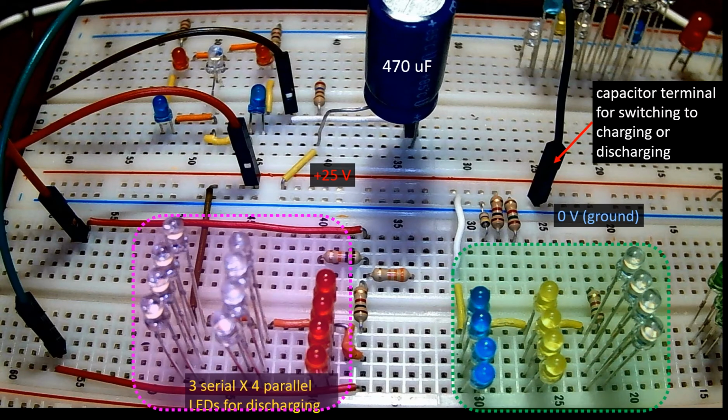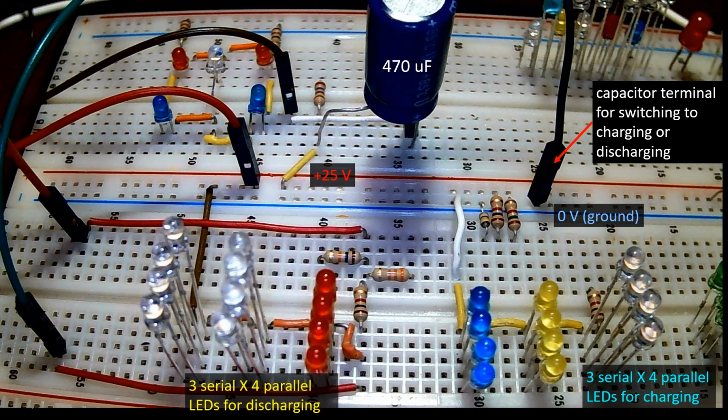and another similar bank of LEDs is used in the path of charging. A number of resistors are also placed in the charge and discharge path in series with the LED banks. These resistors are selectable by moving the capacitor switchable terminal to their contact positions on the circuit board. The resistors allow control of the rate of electrical charge flow, that is, the current. This is similar to what we did in Lab 1.